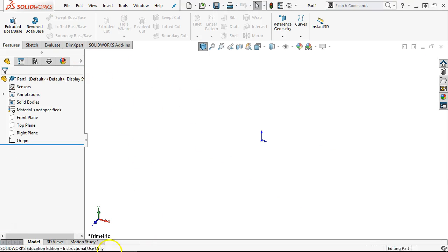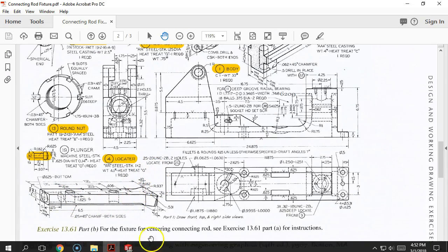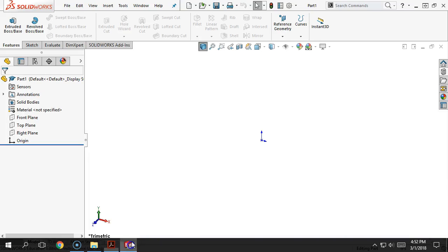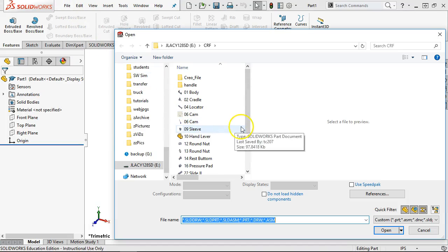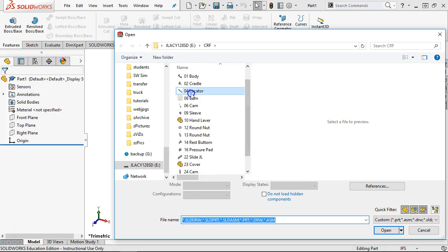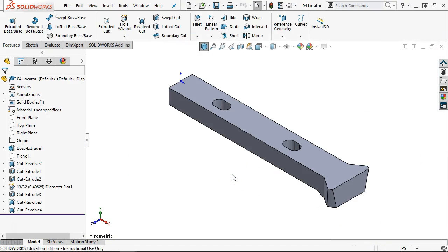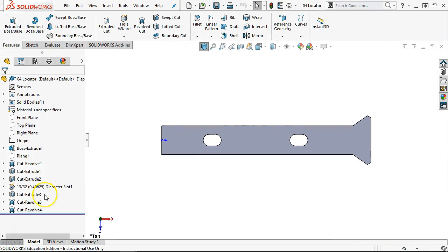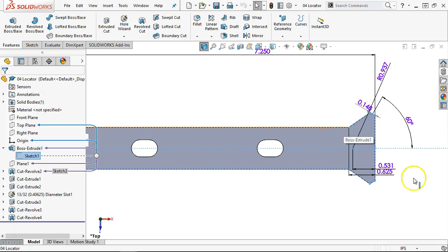Alright, the next one was on the locator. In the process, we found the 30 degrees. So we'll go ahead and pull that locator because when I didn't readily pick it out from that isometric view, I applied a dimension, and the dimension was probably the cause of several other dimensions being less than.